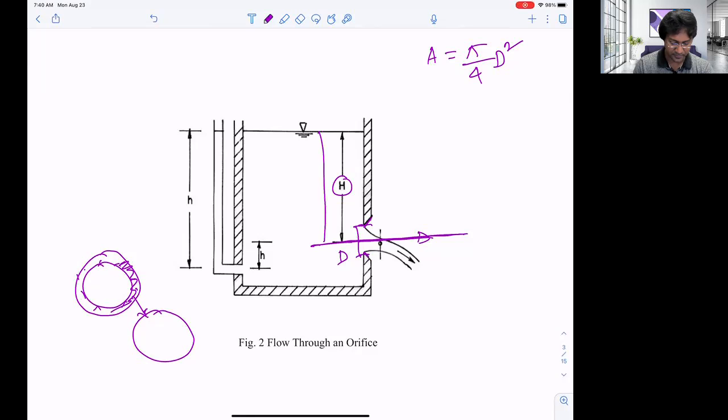We have a setup that has this lower H, or smaller H, outside of the tank. This is the piezometer. It is installed, and the piezometer starts from this level. So that's why we have to measure this difference, right? This difference is called head correction. We know this H prime for this setup, and we have to calculate that H because we need this one. So it will be H minus H prime. Okay, so that is because of the setup.